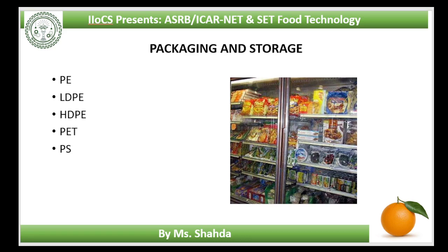Polyethylene terephthalate (PET) is another common material used. The materials are suitable for reheating in conventional and microwave ovens, with stability at temperatures in excess of 250 degrees Celsius. However, the materials are expensive and can become brittle at freezer temperature. Polystyrene (PS) is also a general plastic material used for frozen food applications. Commercial storage of frozen products is usually done in deep freezers at -18 to -20 degrees Celsius.